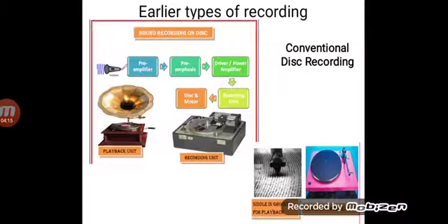So we need to convert those pressure variations into an audio signal, which is nothing but an electrical form of signal. So for that we use a microphone. Now there is a diaphragm placed in a microphone, so that whatever we speak, pressure variations will get converted into an electrical signal. When the diaphragm moves, which is placed in a magnetic field, obviously it will result into a certain electrical signal. Now whatever signal that we get, we first give it to a pre-amplifier, followed by pre-emphasis, where we need to give justification to all the frequency range, then followed by driver or power amplifier.